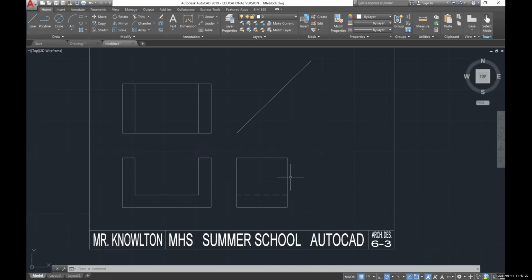I know the width of this is 2 inches. So if I've got a 1 inch window in a 2 inch wall, and my spacing on the left and my spacing on the right is the same, 2 inches minus 1 inch is 1. Then I'll put half of that over here and half of it over here. So I'm going to offset 0.5, so 1/2 inch. I'm offsetting this wall over here 1/2 inch, this one over here 1/2 inch. So that leaves me with 1 inch in the middle. And now from here to here is 1.5. That's where that 1 inch window is centered.